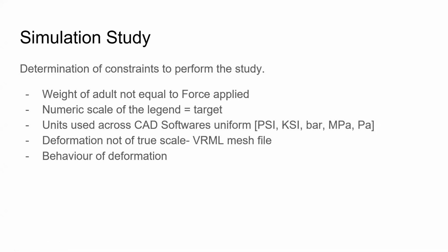We were not sure as to whether the mesh file was of true scale or not, and this process helped us identify the mesh file was not of true scale. This was further verified using the input force and matching the numeric scale of the legend.